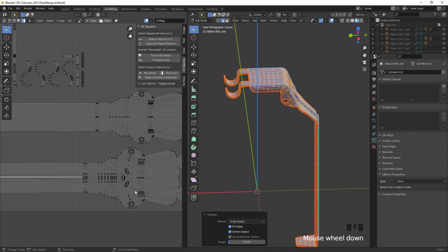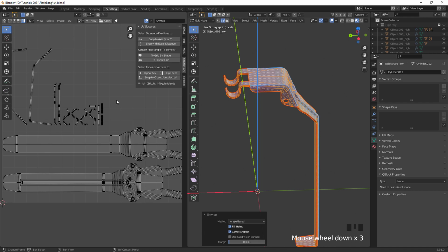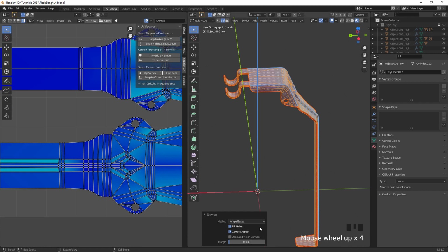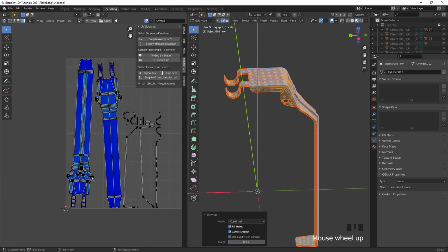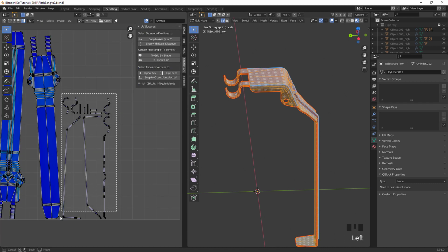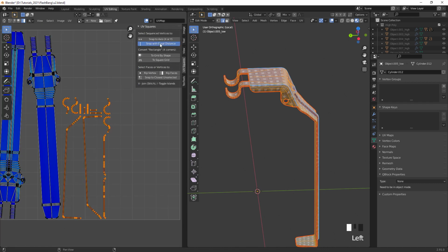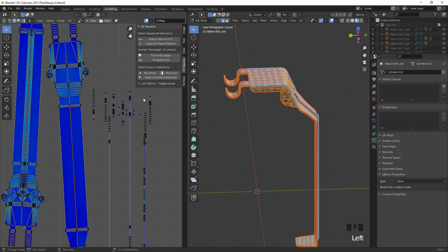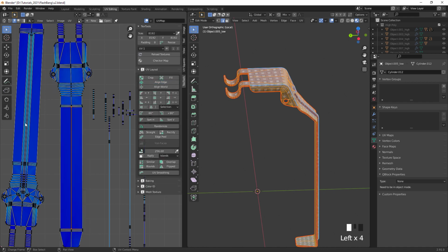And there's another cool view that we have here in Blender. If we want to see what our stretching looks like, we enable display stretch. That shows us where our stretching is. Let's put that to conformal and see if that generates a better result, and I think it does. So sometimes it's a matter of playing around with these methods. Now I'm gonna select all these ones here and snap with equal distance so that we have them nice and straight. Then I'm gonna select this edge here, go to our text tools and align it.